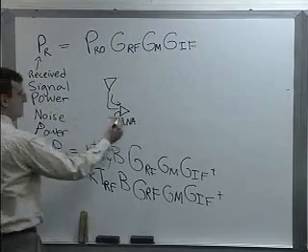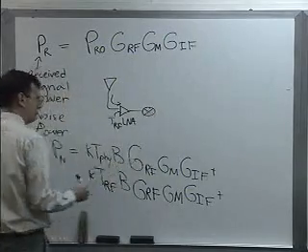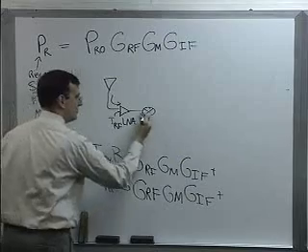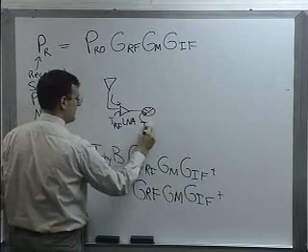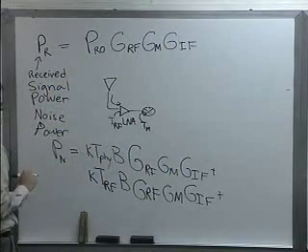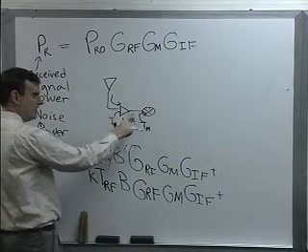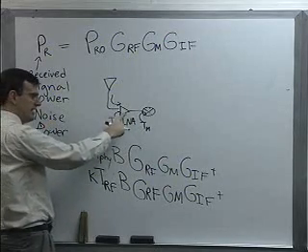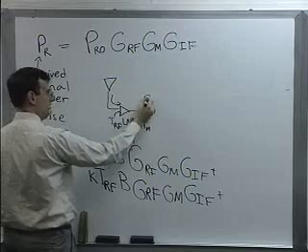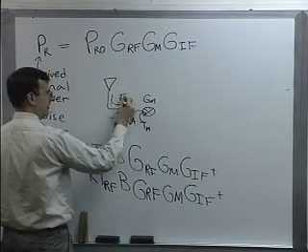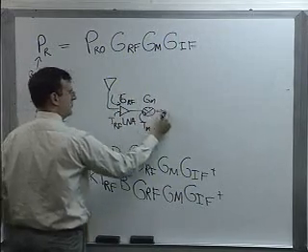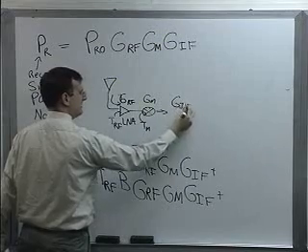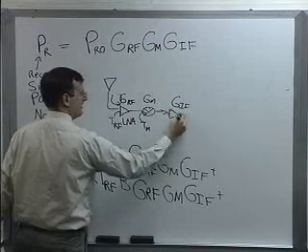And then the next stage is going to hit, that's the mixer. And the mixer is going to add some noise to it. T sub M is going to be the device temperature in kelvins of that mixer. But the mixer hasn't experienced the gain that the LNA has provided. It only experiences our G sub M and what we call G IF, the gain of that next amplifier.